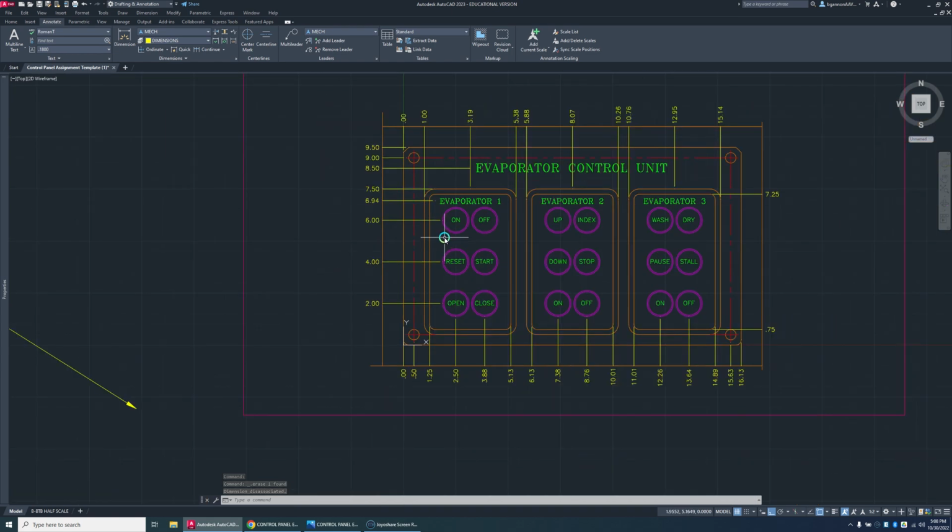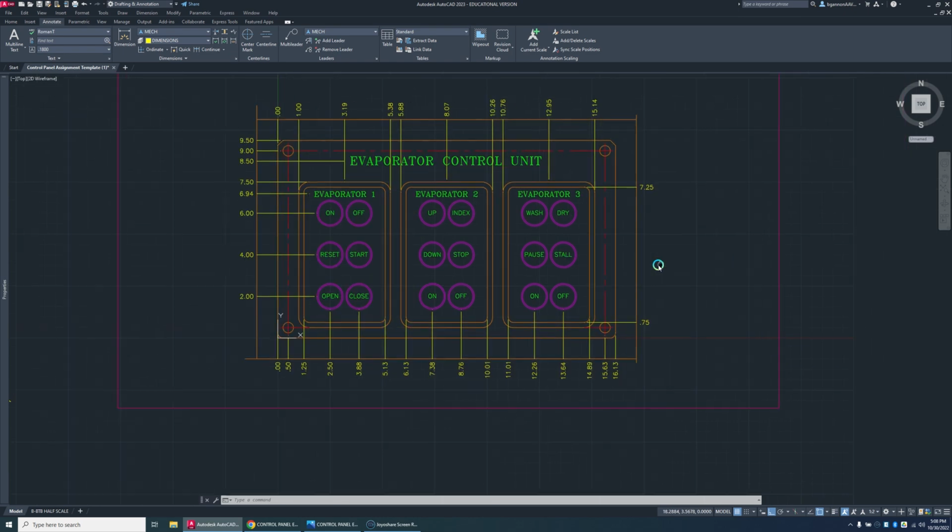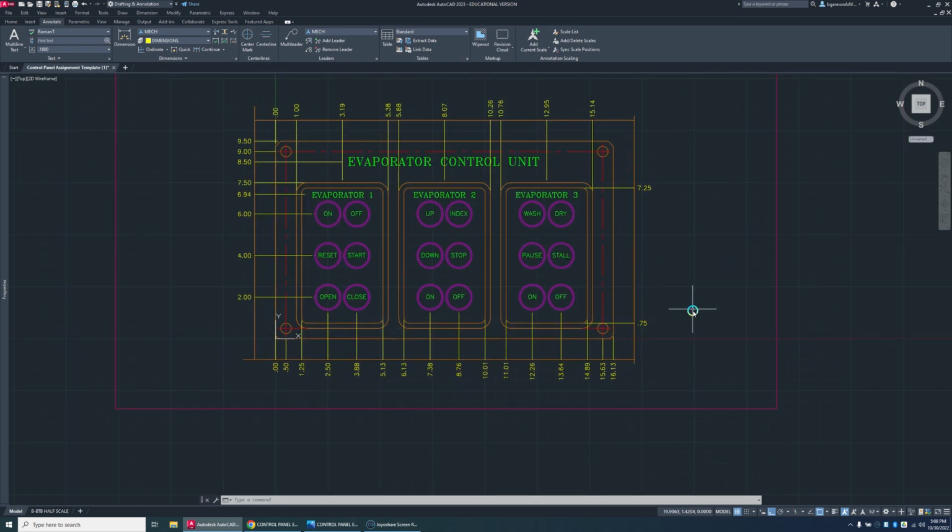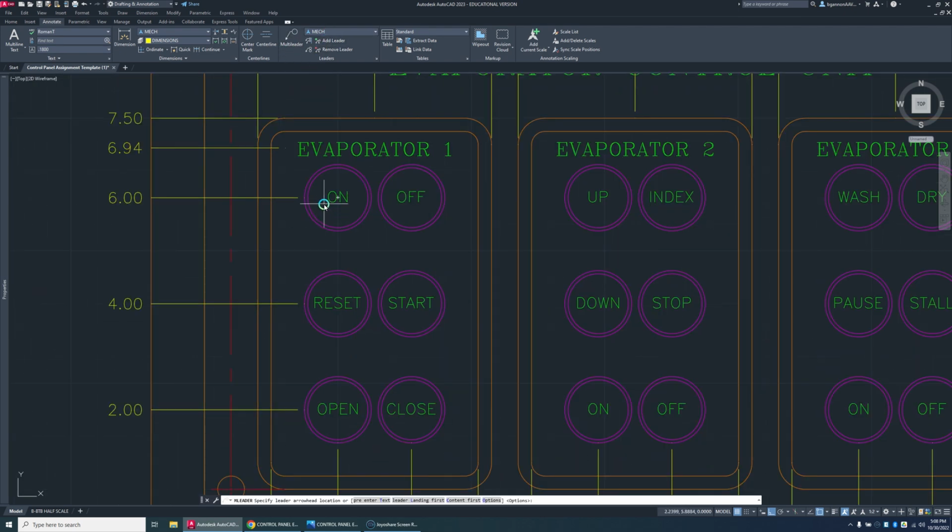Alright, so what else do we have to add on to? We have all of our multileaders on the right side, I believe. So let's start with the radius and our chamfer, and then add everything else. I guess since we're on the left, we'll go on left here. So, multileader, I want to be on the neck layer, and I'm just going to do a multileader here, and it'll point towards the center of this arm.